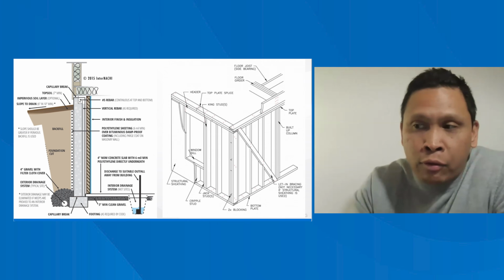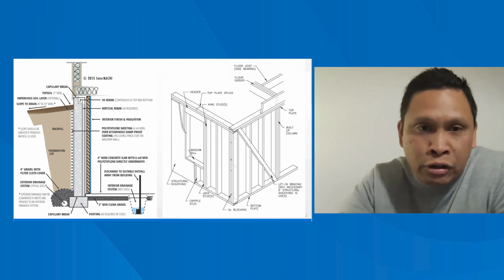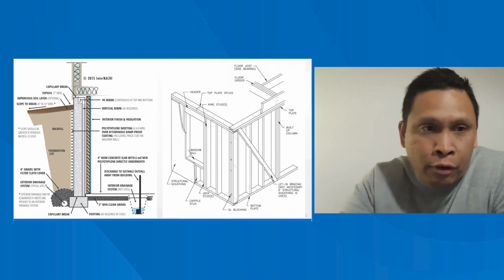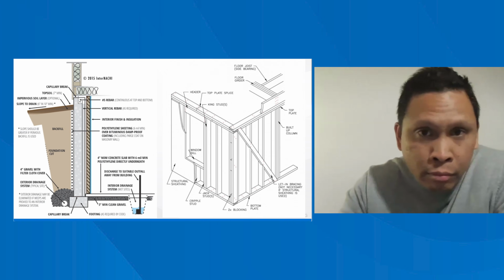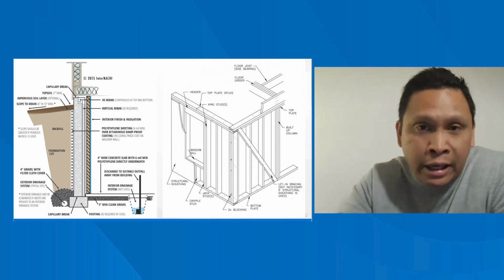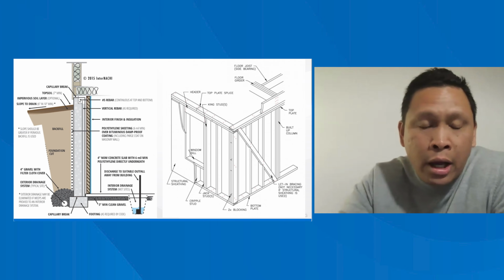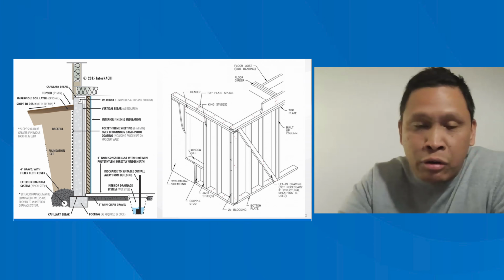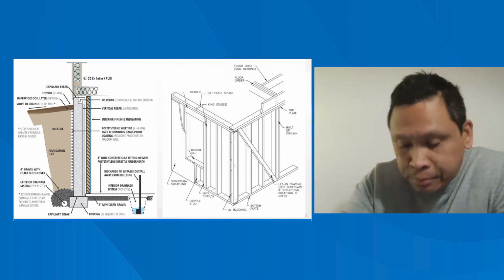So as we all know, water is a food source for biological growth, mold. If water is transitioning into the home because the gutters are not daylighting or discharging the water as far away from the home as possible, then you could have mold in the home, which can also impact the air quality.